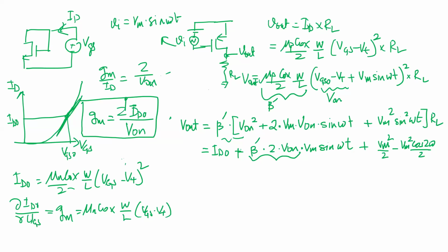So in your audio amplifier, you get a spec called total harmonic distortion. That's the harmonic distortion you have. You've seen how, when you have your rock shows or whatever, and they just blast it, you get this jarring sound. That jarring sound is because of this term here. I mean, you have 2 omega t, 3 omega t, and so on. So let's say I give a pure tone of 1 kilohertz. If you had a perfect linear amplifier, the output should also be 1 kilohertz with a higher amplitude. But now you're going to get 1 kilohertz, then some 2 kilohertz, 3 kilohertz, 4 kilohertz, and so on. And that's the jarring sound you hear in your audio amplifier.